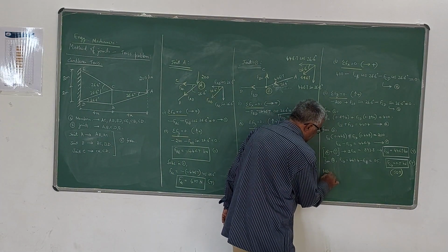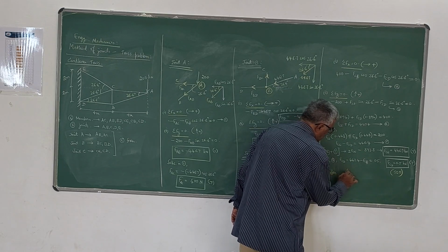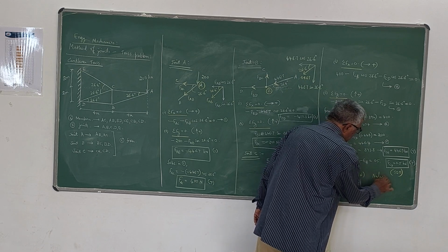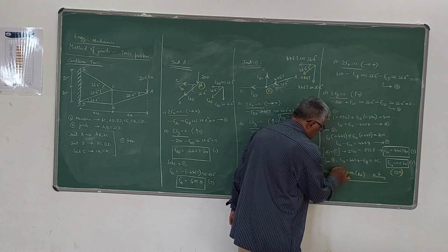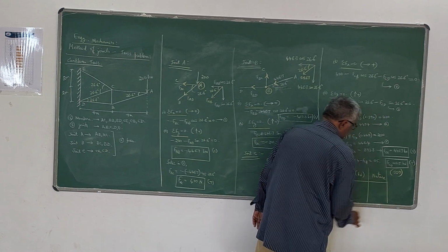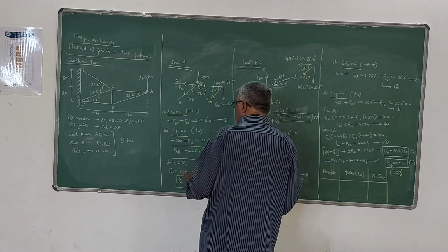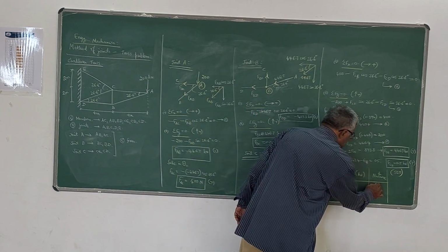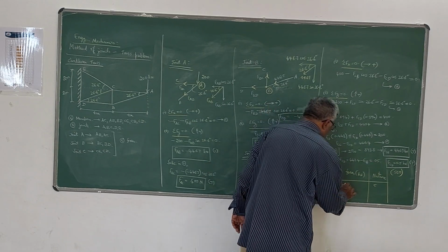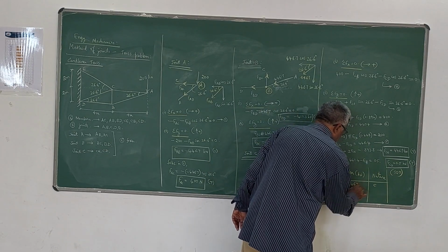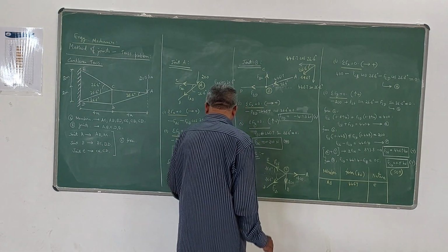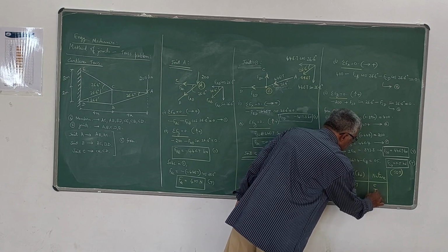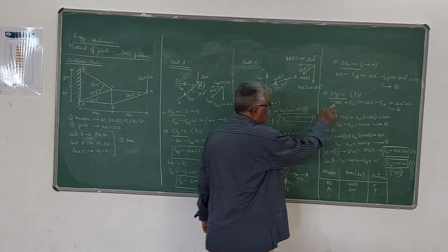Like I have explained in the last problem, remember, forces in kilonewton and nature. So like this, you can have a tabular column. If they ask you to tabulate the values, you just write like this. For example, member AB is compression. You have to write AB here. So it is compression in nature, and the value is 446.7. We only have to write the magnitude, in kilonewton. Similarly, AC is tension, 400. So 400 tension force. Like this, you can tabulate all the other 4 values also.